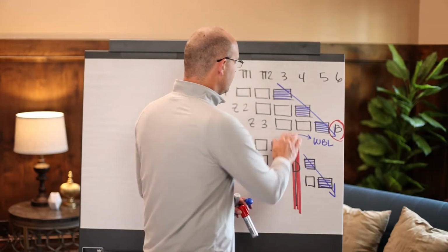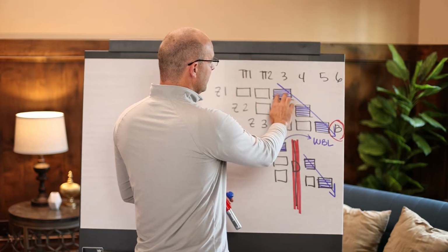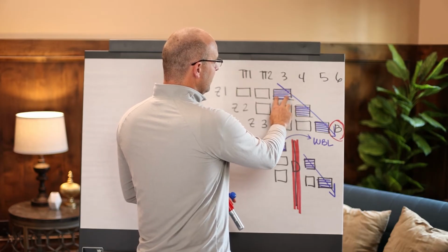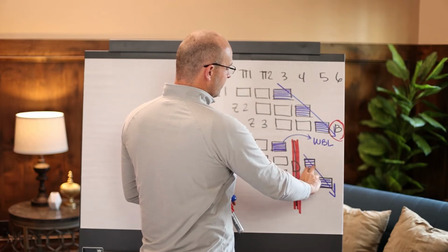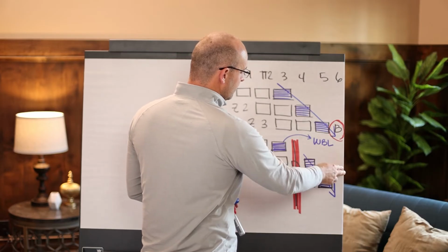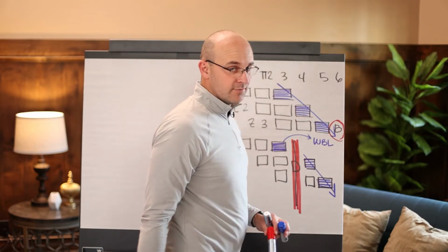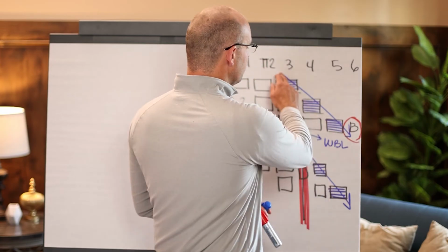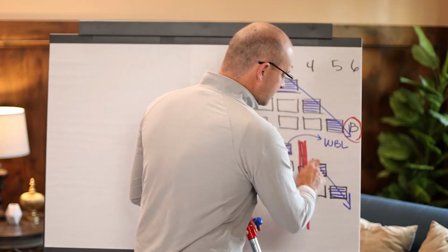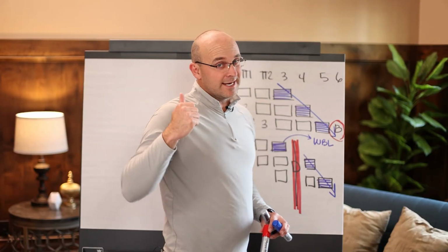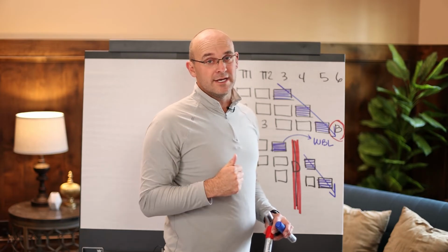The other thing that you can do is adjust this sequence. If there's a delay, ask yourself, will this activity, or for instance, this activity, could it be resequenced in the overall sequence of work? And so if that happens, you still maintain your line of balance, you still maintain trade flow, and that's why that is our #1 option for managing a delay.